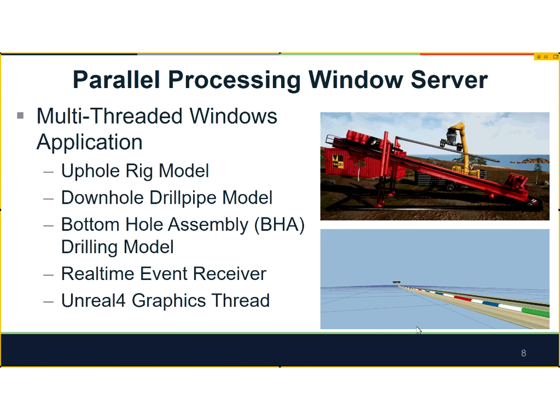Then there's another thread that's basically just modeling the drilling and the orientation of the drill bit and the high pressure jets relative to the end of the borehole, basically the impingement distance between the jet, the expansion of that jet in basically a pressurized volume in front of the bit, and the impingement angle, and basically the erosion, the depth of penetration that we expect to see through jetting, through pushing and turning as it's grinding through whatever is in front.